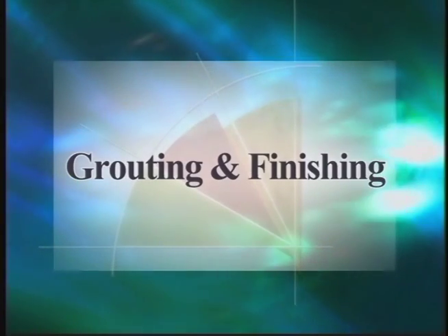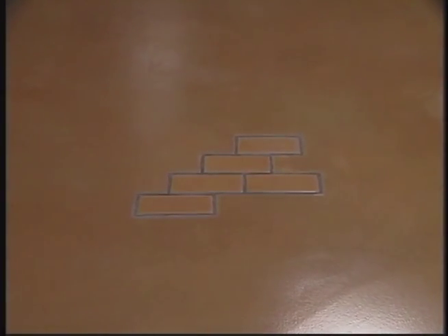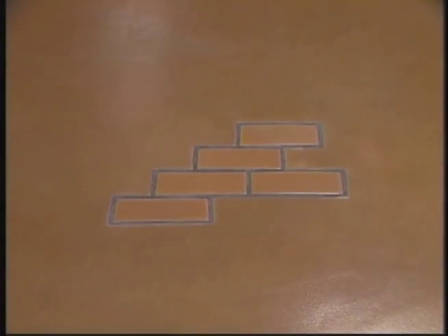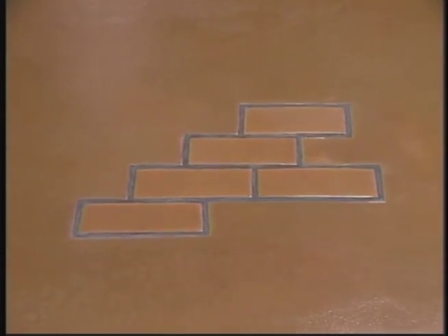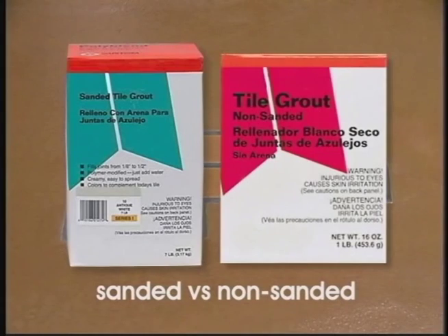Grouting and finishing. Once the sealant or coating has fully cured, grouting and finishes can then be applied. Caution must be taken when grouting. Some grouts contain sand, which may scratch the surface finish. Use a non-sanded grout when possible.